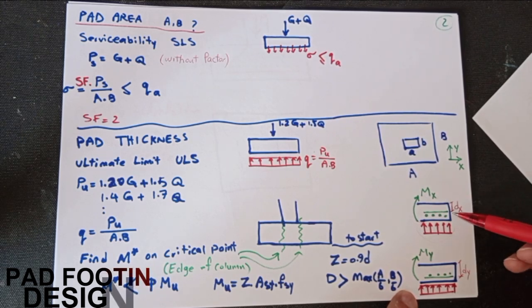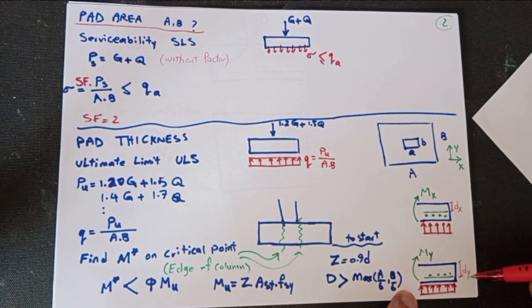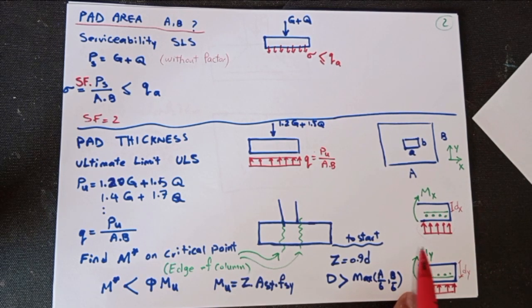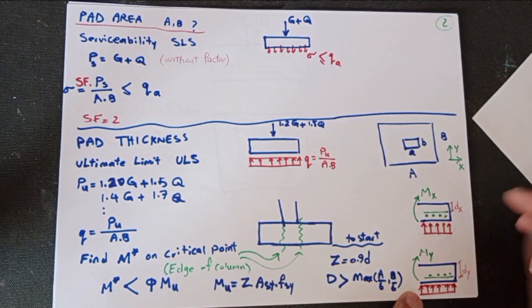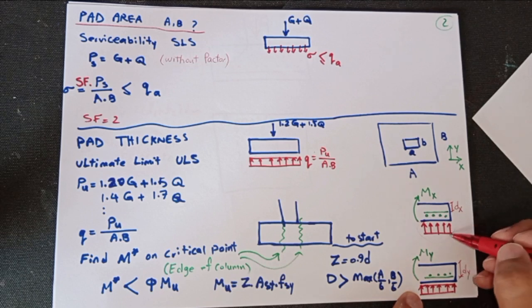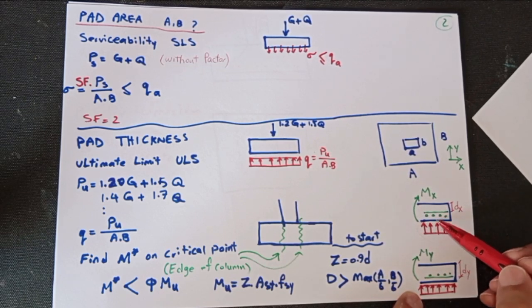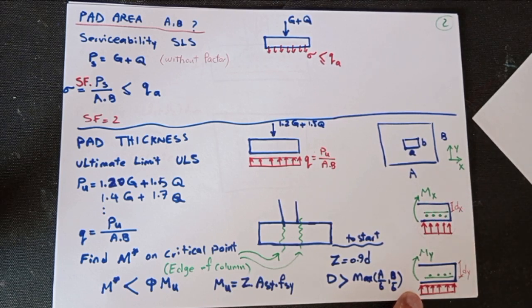Just remember, if we have two layers of reinforcement, one depth, let's say dx or dy, should be short and the other one will be long. So if we have M calculated from this, that is uniform load over this length. You know that it should be Q times this L times half of this distance that will give you the M value. And if you have that one, it gives you the applied design load.